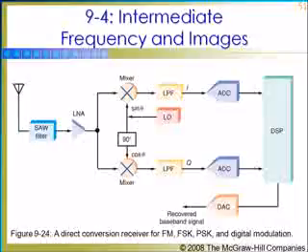The local oscillator signal, usually from a synthesizer, is fed directly to the upper mixer, the sine theta, and to a 90-degree phase shifter that supplies the lower mixer, the cosine theta. As we can remember, the LO frequency is equal to the incoming signal frequency. These two mixers provide baseband signals at their outputs. The double LO frequency signals resulting from mixing are removed with a low-pass filter, this 2LPF. The two baseband signals are separated in phase by 90 degrees.